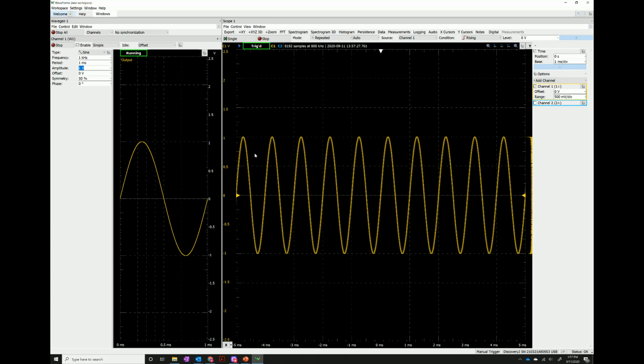Our current setting here on the scope is set to 500 millivolts per division. If we look over in our channel parameters, we can see this by each one of these blocks here representing 0.5 volts or 500 millivolts. So we have 2 divisions above 0 representing this 1 volt peak of our signal or amplitude, and two divisions below 0 representing this -1 volt at the minimum.